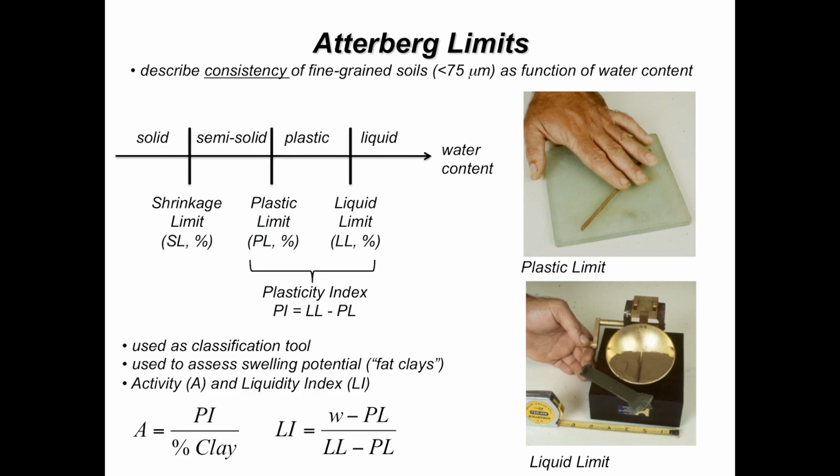Again, just a short description of Atterberg limits. So these are water content values that quantify the boundaries between consistency states of fine-grained material as it changes with water content. So again, this boundary between a plastic state and a liquid state, which we arbitrarily define or identify using this Casagrande method or other methods, fall cone methods, and other approaches that we can use. That's the liquid limit. So essentially, the higher that water content, the more water that clay is capable of absorbing before it begins to behave like a liquid.